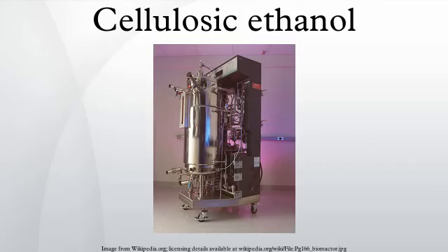Feedstocks. In general there are two types of feedstocks, forest biomass and agricultural biomass. In the U.S., about 1.4 billion dry tons of biomass can be sustainably produced annually. About 370 million tons, or 30%, are forest biomass. Forest biomass has higher cellulose and lignin content and lower hemicellulose and ash content than agricultural biomass. Because of the difficulties and low ethanol yield in fermenting pretreatment hydrolysate, especially those with very high 5-carbon hemicellulose sugars such as xylose, forest biomass has significant advantages over agricultural biomass.